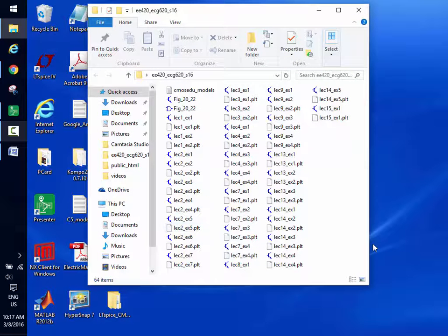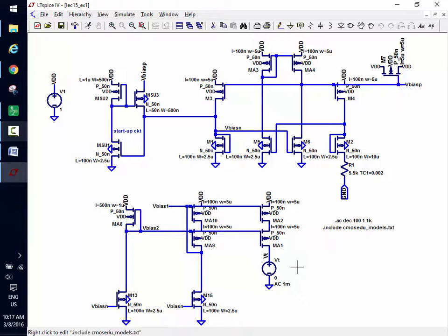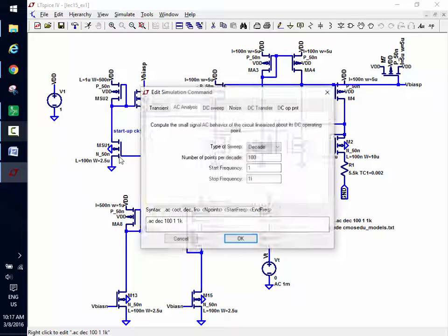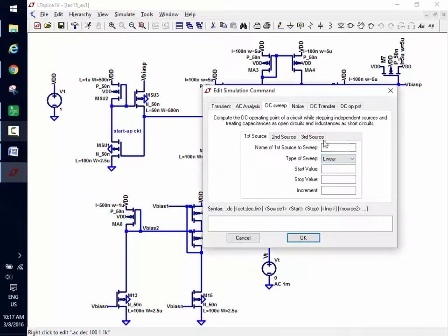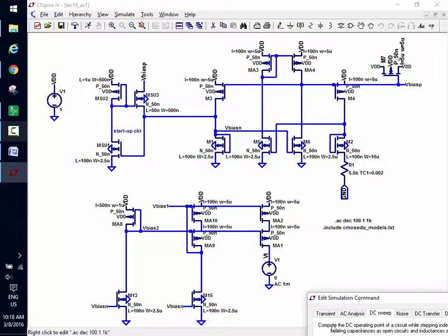No, you said I'm going to look at the DC. You didn't say, when you say look at the DC, I'm thinking dot OP and look at the DC operating point, not sweeping the output, doing a DC sweep. So let's do a DC sweep. So let's go over here, and what do I sweep here? What's V out? That's right, VT. And we're going to sweep it from 0 to 1. And what's going to happen as we get close to 1 volt? Yeah, the output resistance is going to get small.